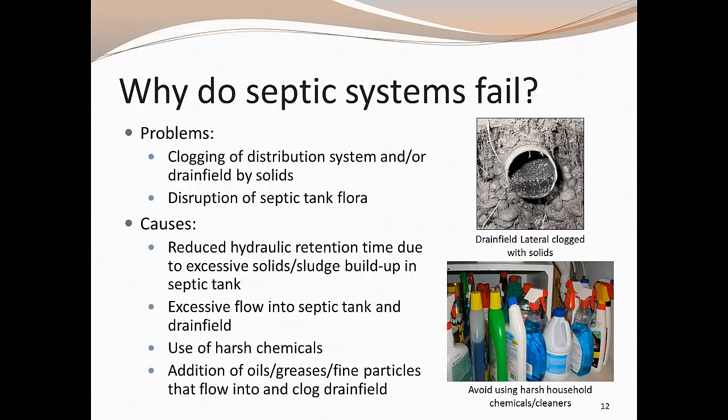The more people there are in the house, the more frequent you should pump it. In addition, take care to keep grease, oils, and fine particles out of your septic system because they can clog the area as well. If you must use a garbage disposal, do so sparingly. Harsh chemicals, including many household cleaners, can be harmful to the bacteria in a septic system. The bacteria in the system are the engine that drives the treatment. Taking care not to harm these bacteria is critical in maintaining a properly functioning system. Use chemicals for household cleaning sparingly.